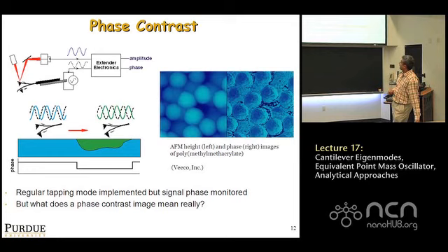So there's a phase difference effectively between the shaking and the response of the tip that you observe. And from the early days of dynamic AFM, it was recognized that as you scan a surface in tapping mode, you're keeping the amplitude constant. Therefore, the phase can change over the sample, depending on local properties. So the very first idea of going beyond topography in AFM came with this idea of phase contrast.